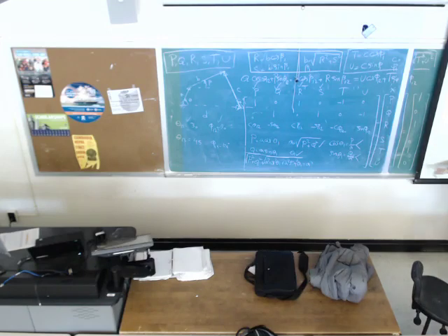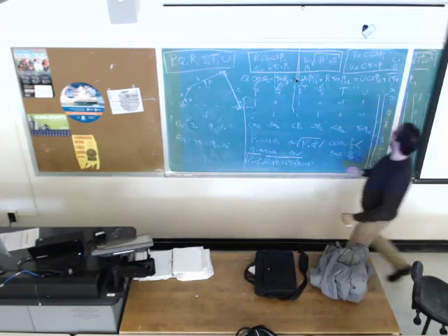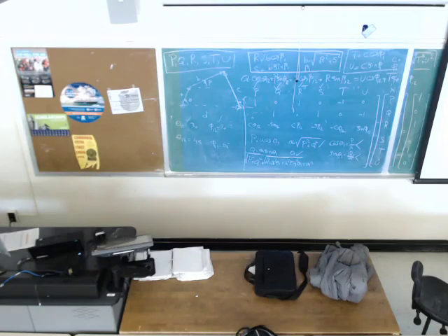Then you are moving by theta 12, which is 30 degrees. From an angle of 61, you end up at 91. So this guy should move by an angle of 90, which is the second precision point. And if you move by the angle of 45 degrees from here, which is 106, this should move by an angle of 120, which is this angle. It's going to represent the third precision point. Good.